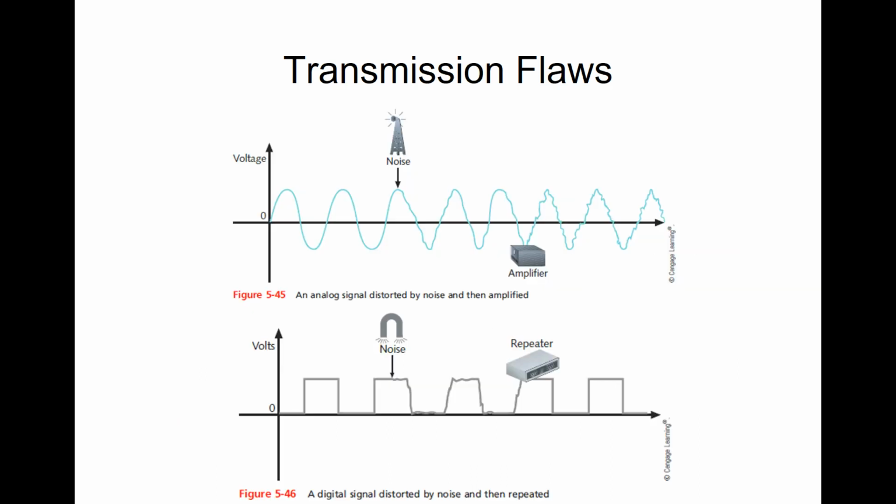And then we have a digital repeater. So an amplifier raises the signal level, but it also amplifies the noise that's in it. So we have limited times we can amplify something before it becomes unusable. A repeater, though, or what we call it in the fiber optic world, a regenerator, we get the signal, so here comes our signal. Even though it's got noise in it, we can still read that as a 0 and this is a 1. And it comes into this repeater and it recreates that signal completely.